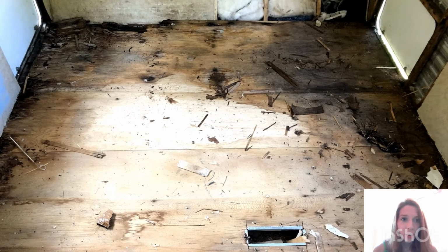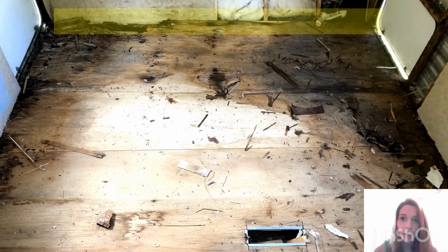So as you can see, this floor had some pretty significant water damage. This is actually the floor from the video that I showed y'all at the beginning of the presentation. So first I determined the leak was coming from a piece of trim that wasn't caulked on the exterior of the camper, right about there where that yellow just showed up. So whenever it would rain, the water would just come down the front of the camper and basically go directly into the floor for a long time.